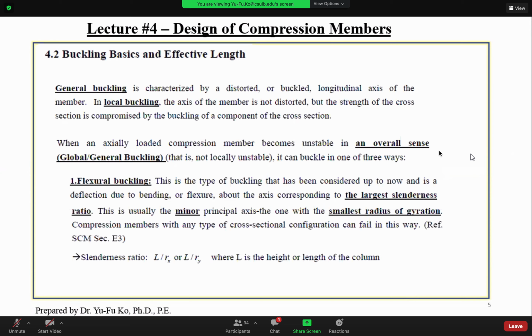So it's a smaller moment of inertia. So with the small I, it's going to have less stiffness, right? Less stiffness depends on what kind of stiffness you are talking about. If you are talking about bending stiffness, yes.